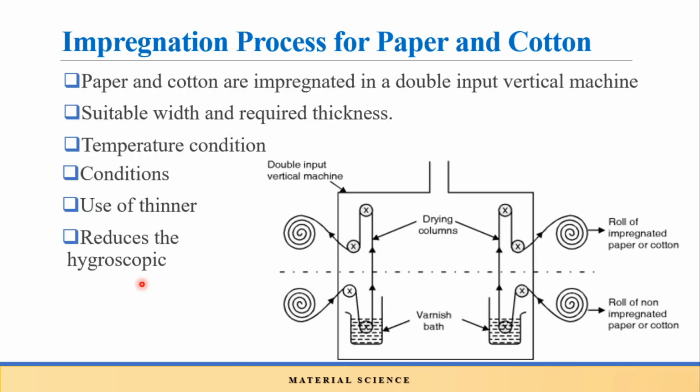Now we will discuss the purpose of the impregnation process. The fibrous insulating materials have air pockets or gaps inside them, which are present during the manufacturing process. It reduces permeability and dielectric strength of the insulating material. The breakdown occurs in these air pockets, making insulation worse. As there is a presence of voids and gaps in the insulating material, it leads to breakdown of the insulating material in worst conditions.